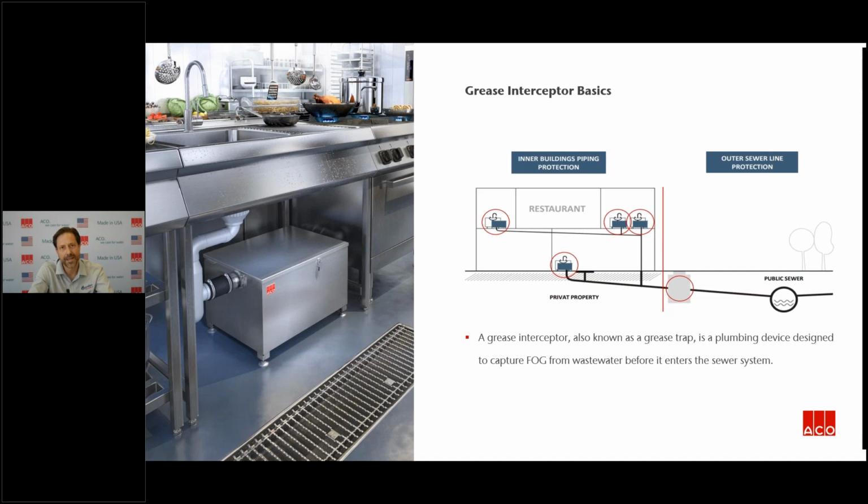I like to look at systems as an organism in some respects. There's pipes, there's networks, there's connectivity. In a building or a project, you have the interior and you have the exterior. And so there are different ways that grease interceptors can be deployed. Sometimes they're deployed right at the source, so at sinks, at dishwashers, before the outflow out towards your sewers, or you have a main containment, which perhaps is outside of the building envelope, usually in ground, and is essentially trapping the grease before it enters the sewer.